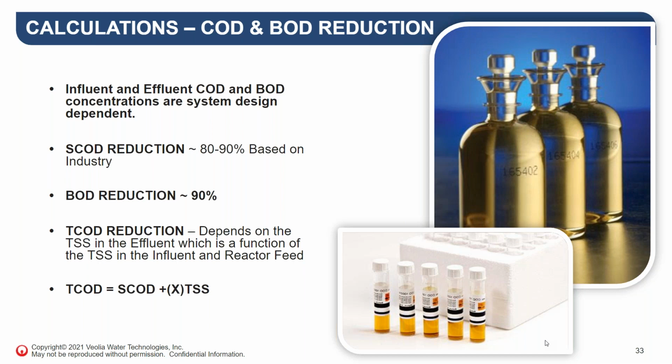Yeast production is a fermentation process where they mainly use molasses as the substrate to grow the yeast on. In that case, the COD to BOD ratio on the influent could be somewhere between 2 and 3. And that means that there's a lot of COD that's not degradable biologically. So you'll see a COD reduction of maybe 65%, but the BOD reduction will still be 95%.